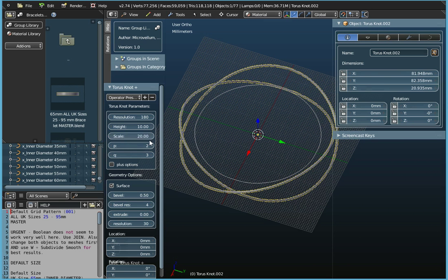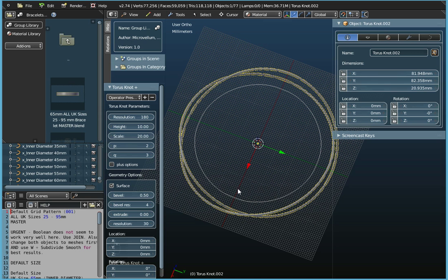Now what you find with this value here, if I type in a particular value of say 20, if you notice over here, the X, the red value, taken from the outside of the curve, is about 80 millimeters, and the Y as well is about 80 millimeters. So this value of 20 here, essentially you've got to multiply it by 4 to give this value of 80.